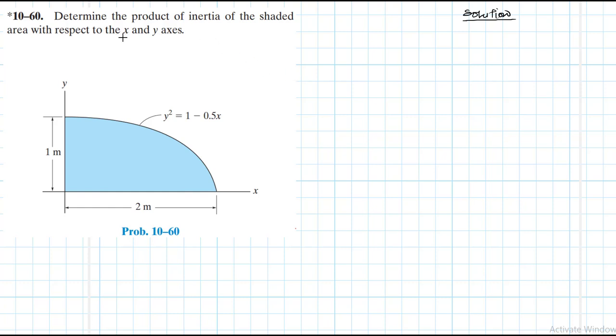but this one is mainly used for determining the maximum and minimum moments of inertia over an area. These maximum and minimum values of area moment of inertia are important properties needed for designing structural and mechanical members or elements such as beams, columns, and shafts.